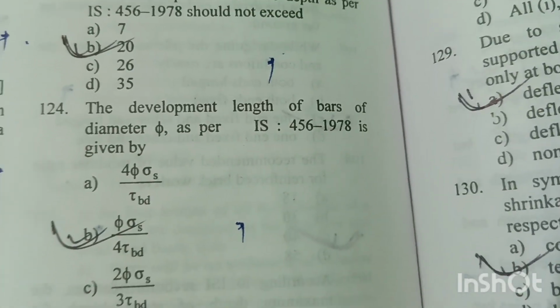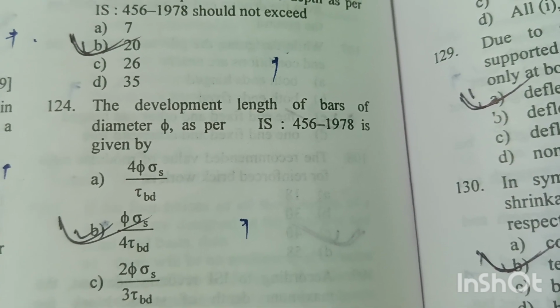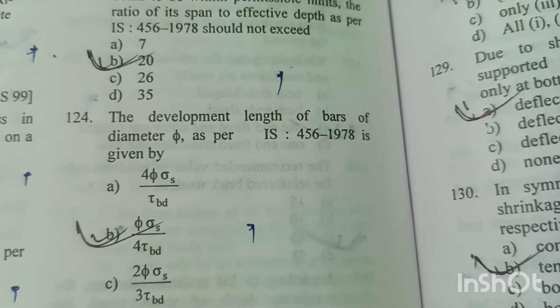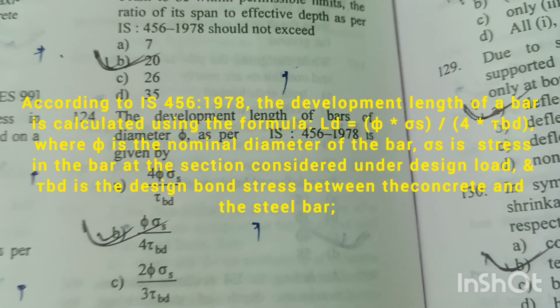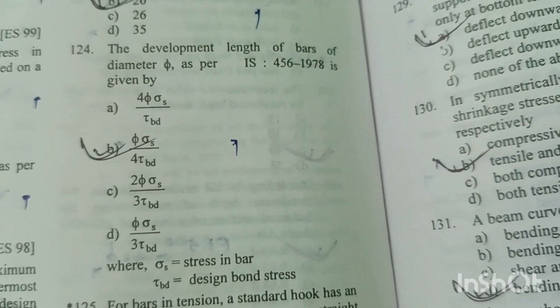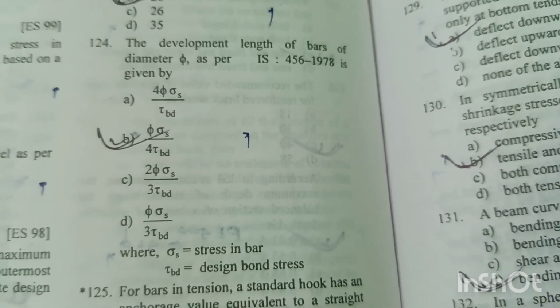Question number 124. The development length of bars of diameter phi as per IS 456 1978 is given by. Option B is right answer, phi sigma s divided by 4 into tau Vd, where tau Vd is the design bond stress and sigma s is the stress in the bar.